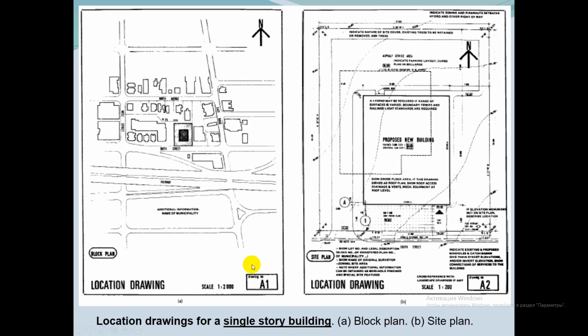Construction survey for a single-story building may only entail survey layouts for the building footing and ground floor elevation, and the contractor can tie in the rest of the building components to the footing and the first floor elevations for both line and grade. Of course, site grading surveys will also be required in most circumstances.